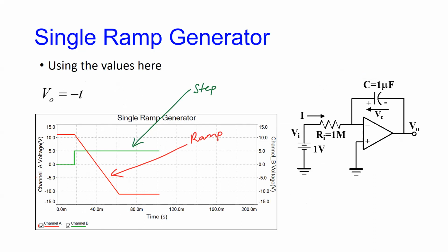And if you plot it right here, which is what I did, you put the circuit and you simulate the circuit, you could see that once you put this step voltage in, you find a way to increase the step. As I said, a simple switch would do. As the step goes in, the output of the op-amp starts to decrease very linearly until it moves from plus VSAT, whatever is the saturated output of the op-amp, to negative VSAT.